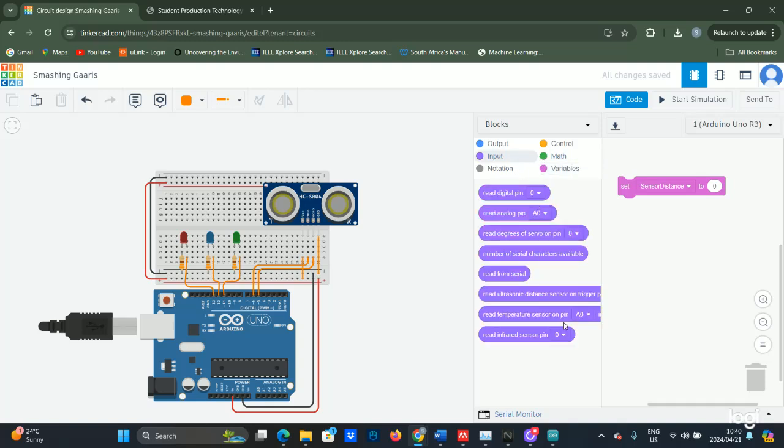Now, as you can see, we have the ultrasonic read block. This is going to define our trigger and our echo pin so it's able to measure the distance. You still remember how I just explained how the ultrasound distance sensor works. So we're putting it here. Let me try and reduce this. Okay, now it's fine.